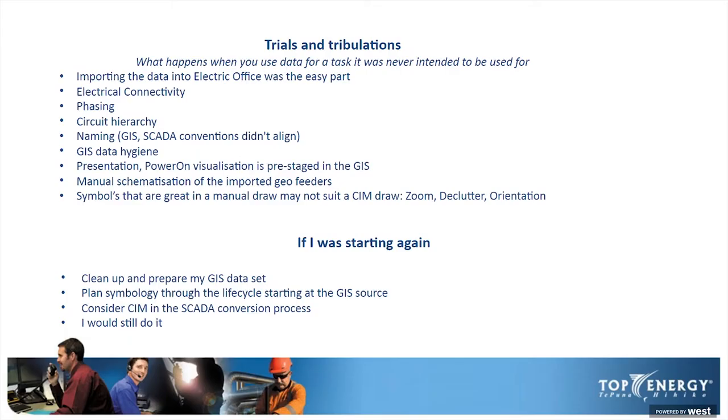circuits into our network. And we'd actually gone quite a long way there before we observed that the ADMS is actually phase aware. And so we didn't have any connectivity between our points of supply, where I had inconsistent phasing in a fuse set. So you'd have a two-phase fuse heading to a 3-phase transformer, so you didn't have consistent phasing all the way through there. And that was endemic throughout my data set, where we hadn't maintained phasing continuity through things.